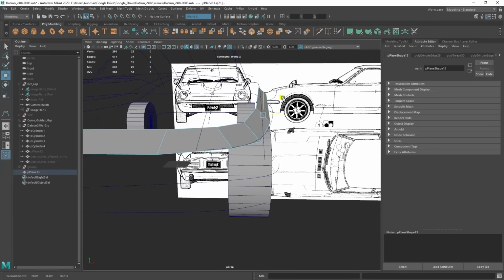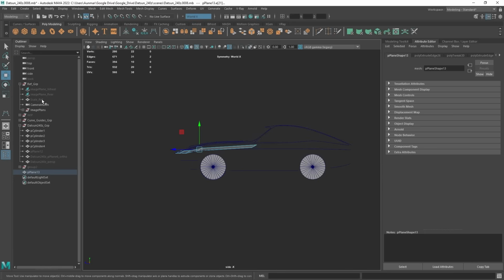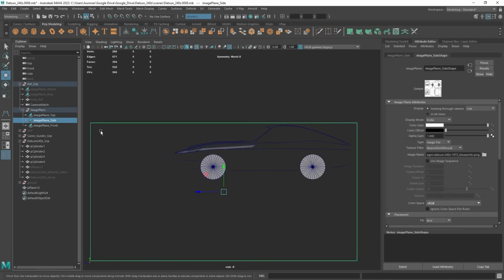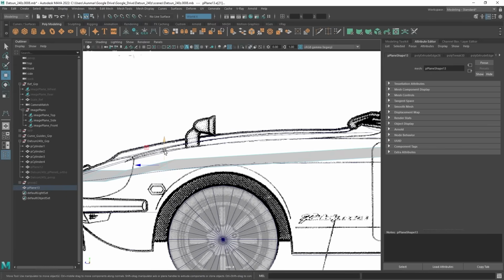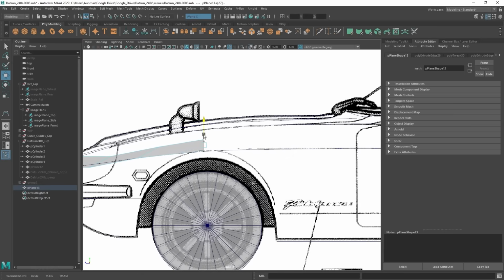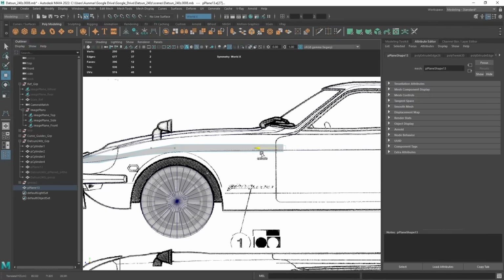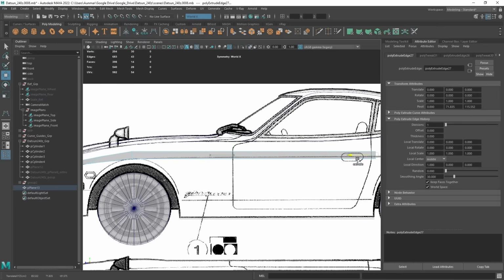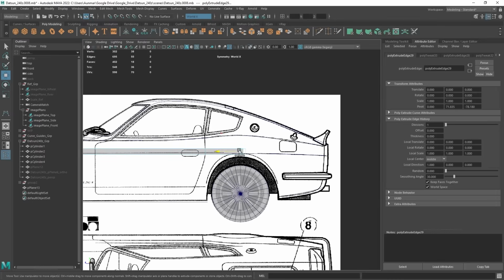So again, we're just going to move this in 3D space, and this is going to help very, very much and help significantly, right? So if I grab this image side, it's just being a little stubborn right now, so I'll work with this, and we can keep this aligned with our reference, and I can scale this so it's nice and flat, and I'm going to keep this right on the midpoint of the wheel well, and I'm going to continue to shift copy. I'm just holding shift and move, shift and move. All right, and we want to eventually get down to the rear of the vehicle,